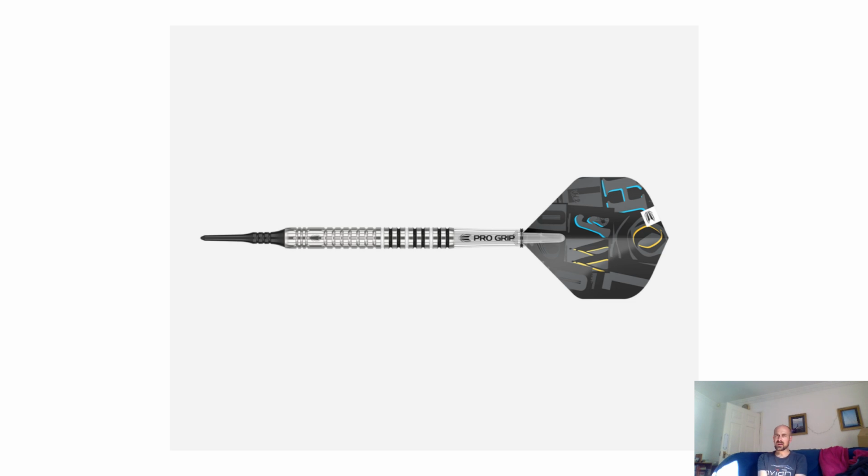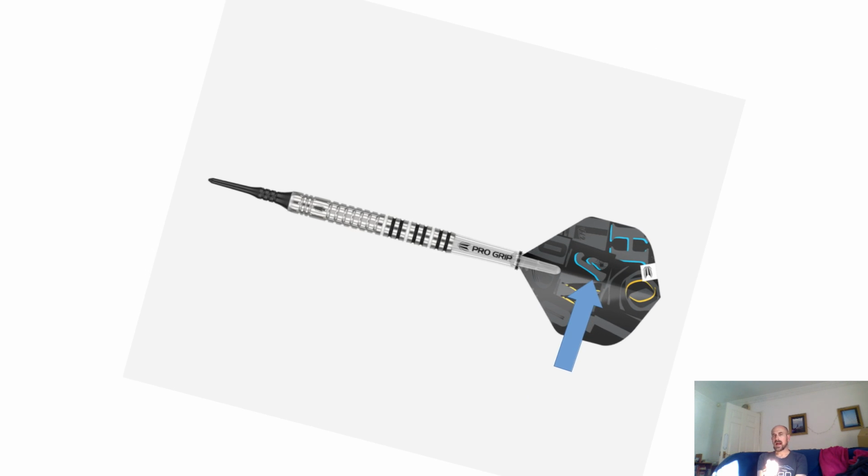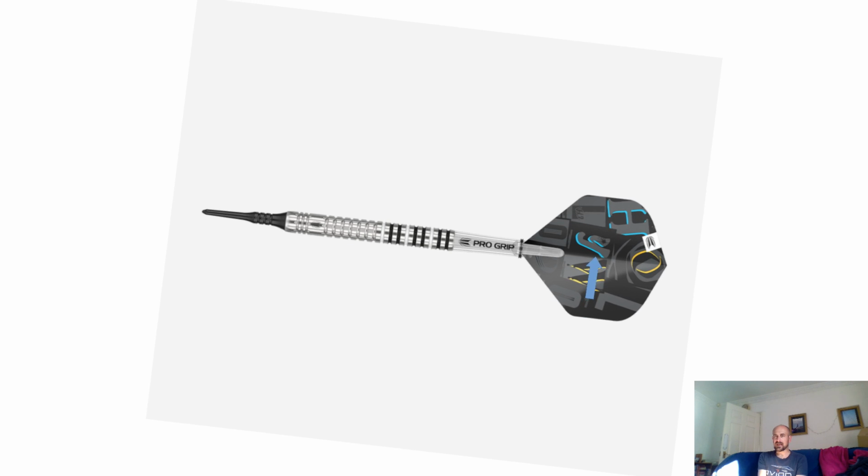Let's start off by thinking about just a simple dart. A dart is something which is obviously aerodynamically stable. It's intuitively easy to understand how it stabilises itself. If you imagine something happens and it gets a little gust and the front of it comes up and the back of it goes down, well, the air's going to push on those flights and it's going to tip it back to level again.